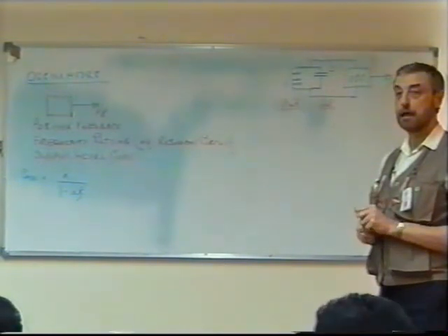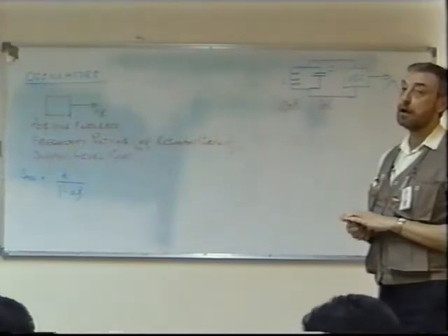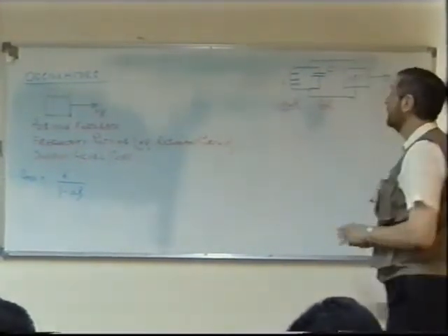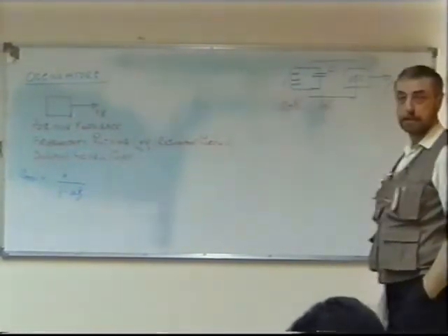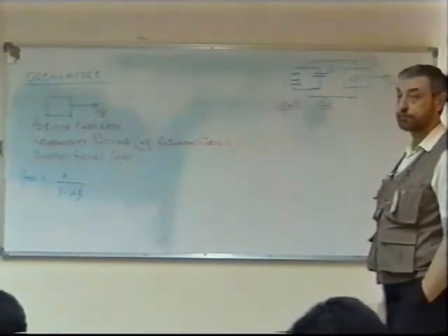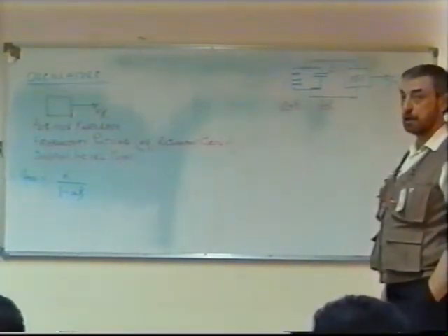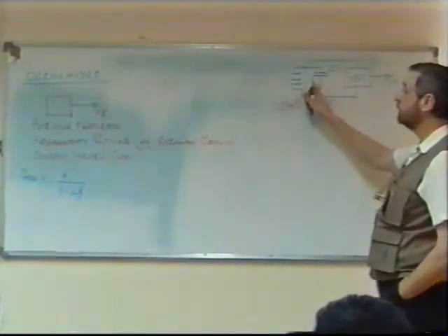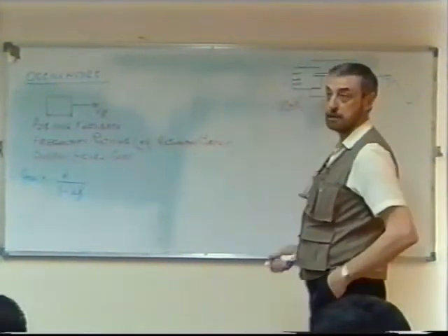The signal is supposed to come outside the inductor and the capacitor. Not necessarily. It depends on the design of the oscillator. I haven't gone into the details of the design, as long as we're using an inductor and capacitor. Isn't the oscillator going to create a lot of harmonics, and we are going to use one of those harmonics? No, that won't create harmonics, providing we make sure that our level is correct.